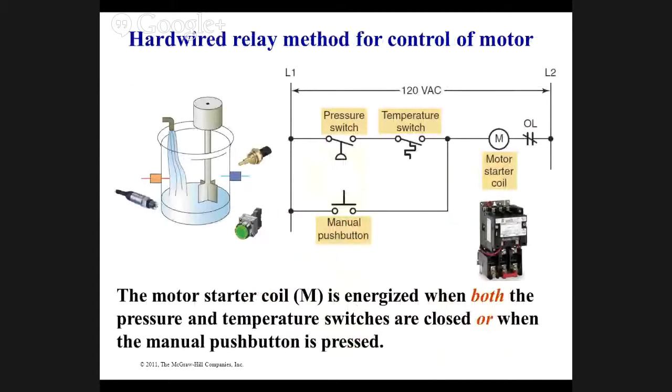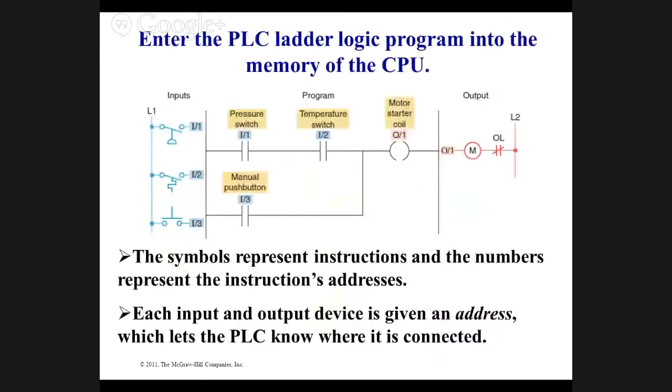Normally open switch. The only difference between the program and the schematic is that we have schematic symbols, while in the program, they're all the same. We simply label them. So look here, normally open, motor comes on. Normally open push button bypasses everything, motor comes on. Over here, same deal, just got labels. So that's the whole premise of ladder logic. If you can read line diagrams, you can read ladder logic. They read just like a book, left to right, top to bottom.